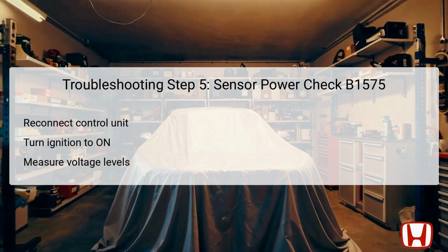If this condition is met, the automatic lighting sensor is functioning correctly and does not require replacement. However, should the voltage deviate from this expected range, it indicates that the automatic lighting control unit must be replaced. This step is vital for determining whether the problem originates from the sensor or control unit.